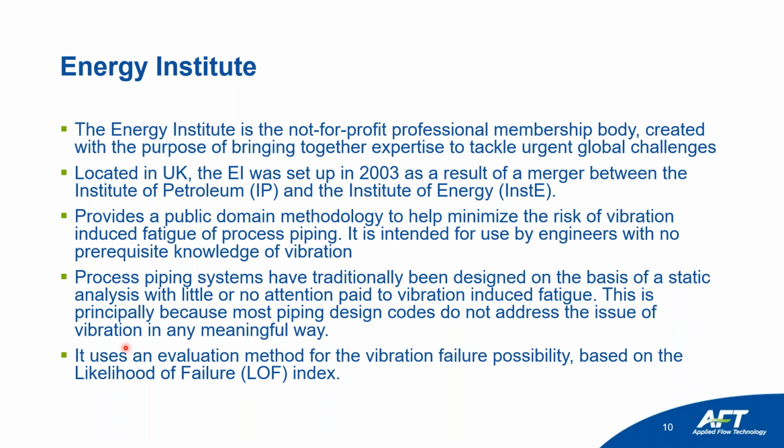So the Energy Institute guideline uses an evaluation method for vibration failure possibility based on the likelihood of failure index. Depending on the index, it has certain measures to be taken depending on the value of the LOF obtained using the method. The Energy Institute guidelines provide a staged approach.